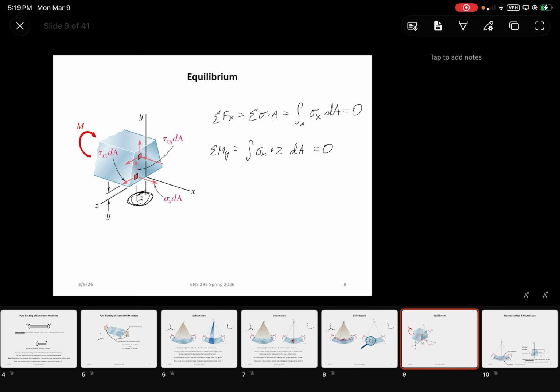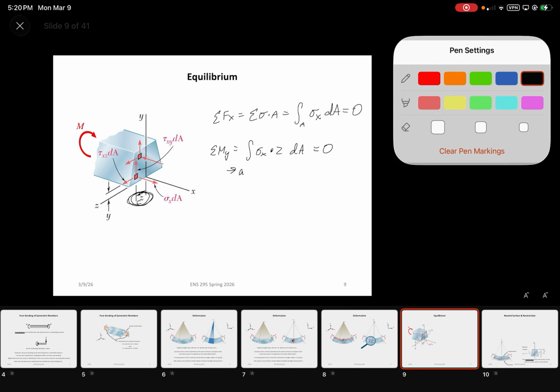Again, if we're dealing with a perfectly symmetric cross-section, guess what? That z doesn't exist. Z is like an eccentricity, you can say. Like if you have a very non-symmetric cross-section, for example, you guys ever see steel channels? Something like that would produce some type of stress eccentricity within the cross-section that you would need to consider. But if you're dealing with something like an I-beam or a 2x4, that z is not going to be present. So this is really going to be only for non-symmetric cross-sections, which let me just...